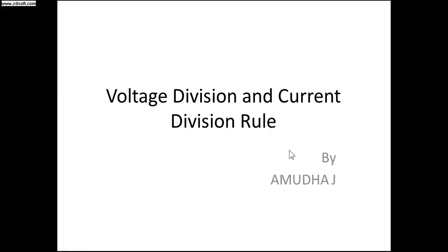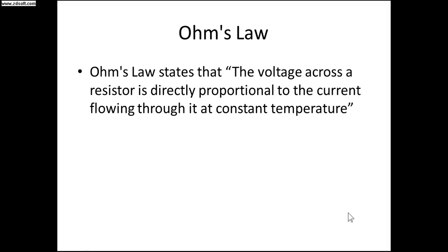Good evening. Today's class is all about the voltage division rule and current division rule, and this is an application of Ohm's law and Kirchhoff's laws that we have learnt in the previous class. Just to recall, what is Ohm's law? The voltage across the resistor is directly proportional to the current flowing through it at constant temperature.